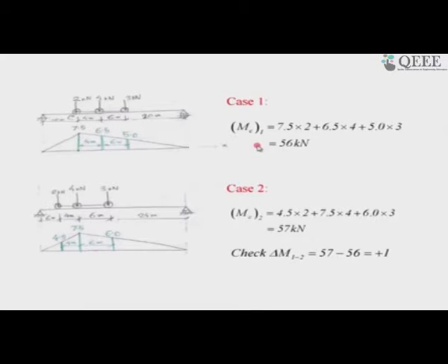I am not going to explain in great detail, because I have already given all details for shear forces. You see, I have placed the loads in such a way that this 2 kilonewton load is just at the right at the section, so that I gain maximum here. Now, unlike the shear forces, I do not have a great loss if I just come towards the left. So, if I neglect the just left and just right, I am sitting right on C, and that is why I have the same value of the ordinate here.